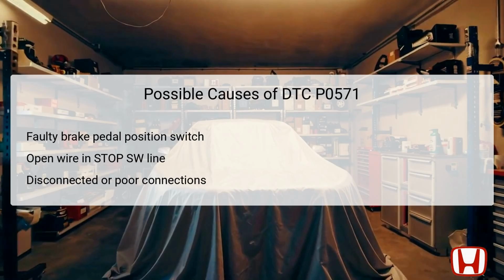It's essential to examine the wiring and connectors for corrosion, breakage, or other issues that may impede proper functioning. Identifying these root causes is critical for accurate repair, ensuring that the brake system operates as intended.